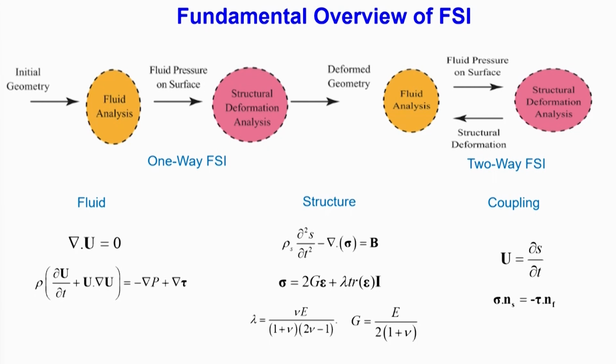And the force balance is that the stress dotted with the normal. This is the normal stress balance, as I told you, that the normal stress in the fluid is equal to that in the solid, equal to minus the pressure. That is what it is writing in a general form. Taking the dot product with the normal direction means it is taking only the normal component. B is the body force per unit volume, whatever small b I had written in the previous slide, that is this b.